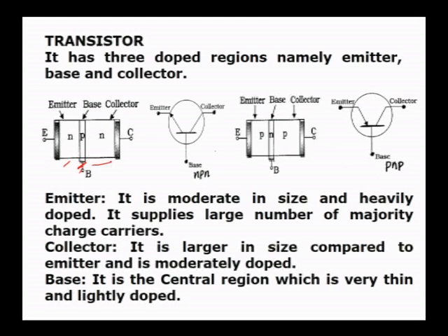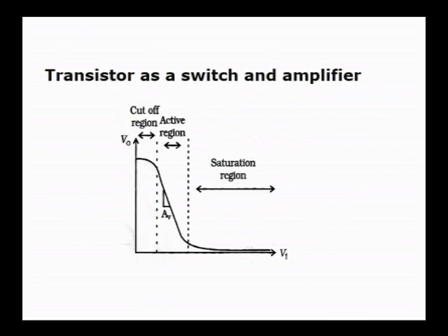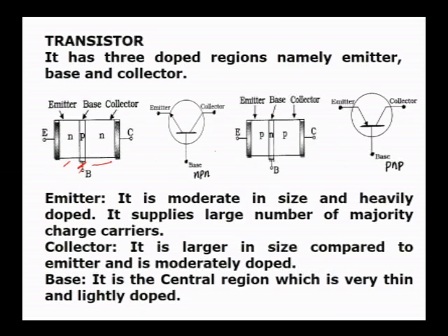And usually transistor is used for amplification purpose. And one more thing is, in case of the distinction, NPN and PNP transistors are the two junction transistors that are available. They are also called bipolar junction transistors, BJTs, and the circuit symbols you have to be careful about. Here the arrow is shown outwards, here the arrow is shown inwards in the PNP transistor.